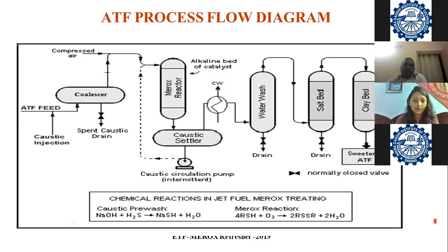So every reaction occurs in the reactor, and the temperature zone evolved is about 60 to 75 degrees centigrade. The catalyst we are using is generally called Merox catalyst. It is a highly patented catalyst which we are taking from America. Our bottle cost is around 40,000 to 50,000, and the recycle period of the catalyst is about 3 to 4 years.